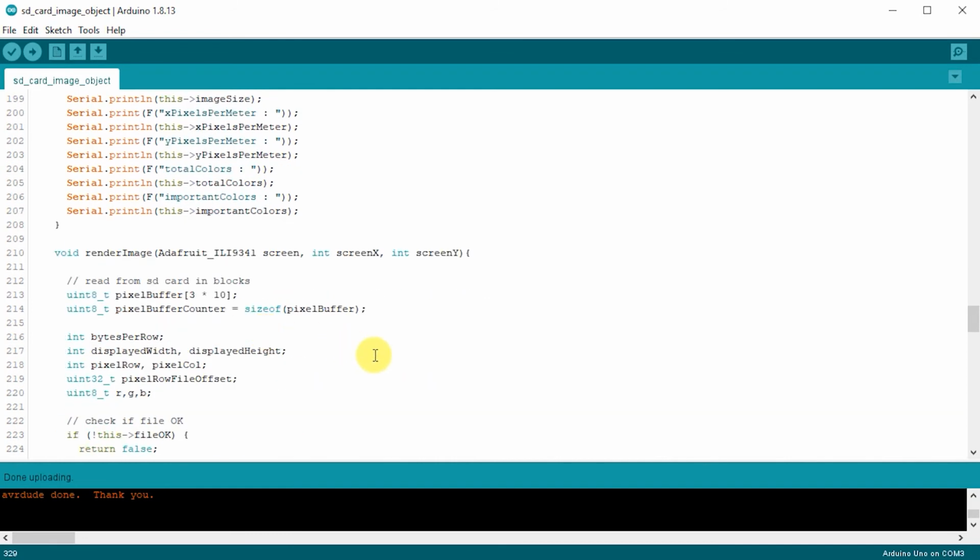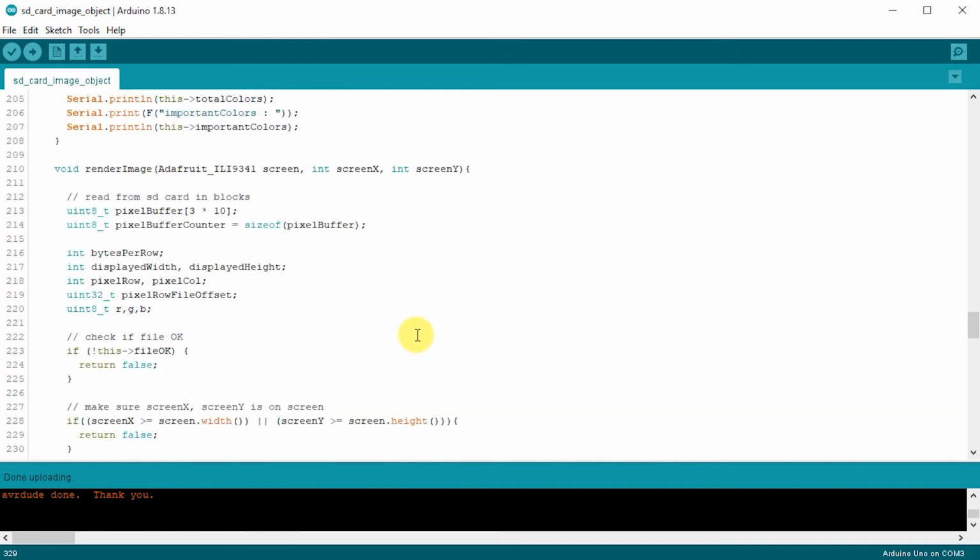Our class here, we may eventually want to extract that out and make it into a little standalone library, which we can then simply import into other Arduino projects. Now, if this library is relying on there being a named global variable, TFT, then obviously our other software has to have that global variable as well. So our library is now dependent upon a certain number of variables being in existence in our sketch, and that is not a good way to code.